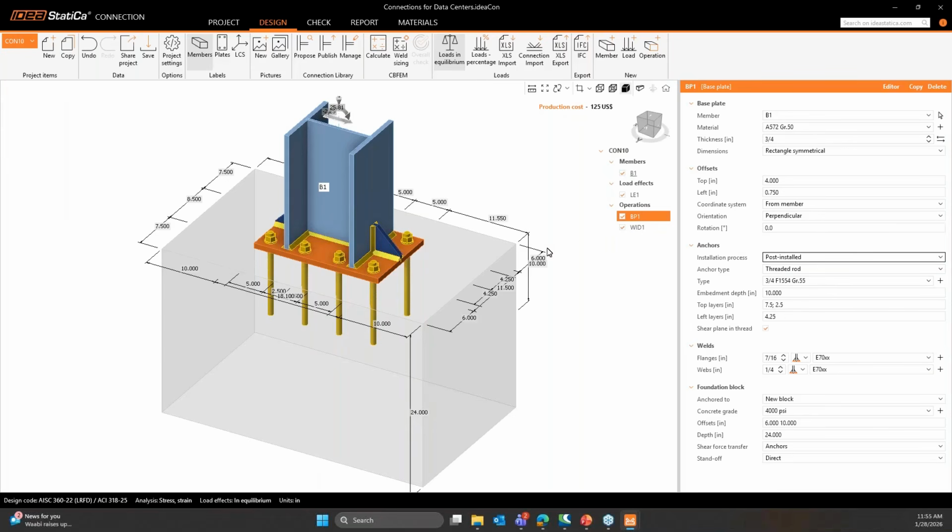That way you can check the steel components here, and then if you want to assess the bond strength of that post-install anchor, you can export your results into Detail 3D, add the reinforcement in your concrete, and then run the analysis and prove your post-install anchor works. From there, we'll be able to check the bond strength of that post-install anchor and provide you a pass or fail check.